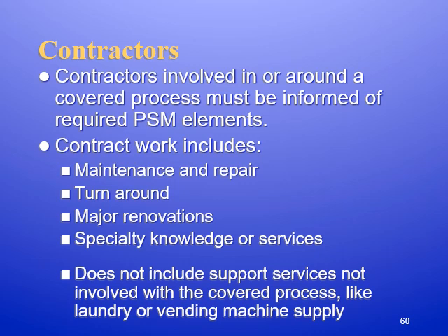Contractors: if you will work at a facility, especially a large facility, you may see a lot of contractors there. Contractors involved in or around covered processes must be informed of required PSM elements. They're going to be working there. They must know. Contract work includes maintenance and repair, which happens a lot, turnaround, major renovations, specialty knowledge or services. It does not include support services that are not involved with a covered process, like laundry or vending machine supply, obviously.